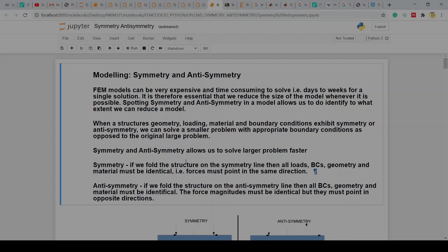When it comes to sparse matrices, finite element matrices are typically sparse. What it means is they have a certain bandwidth. It's not like a full dense matrix where all the values are non-zero. Around the diagonal, there's a big highway of numbers that are non-zero. The rest far out are typically zero, especially if we've made the effort to make sure the mesh is properly partitioned. In those cases, solving a matrix typically scales as n times the bandwidth squared. The n is the thing that could change if I change the size, but the bandwidth might also change when I have a larger system that I need to solve.